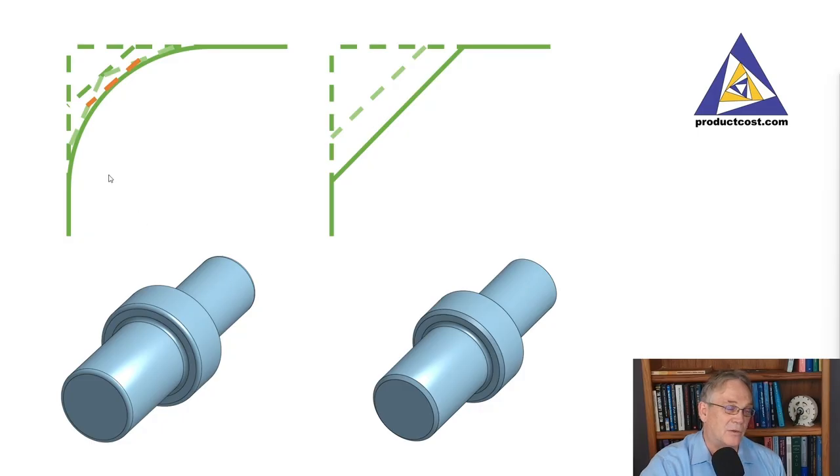If you have a fillet and you use a flat tool, this is however not the case. You'll do your initial pass over here, and then you'd have to do another pass here, another pass here, yet another pass. Once you do all these passes, you still don't have the fillet shape. You still have a 3-cornered or 4-cornered part on each of these fillets. You'd have to do multiple more passes to get a more accurate rendition of the round feature here.